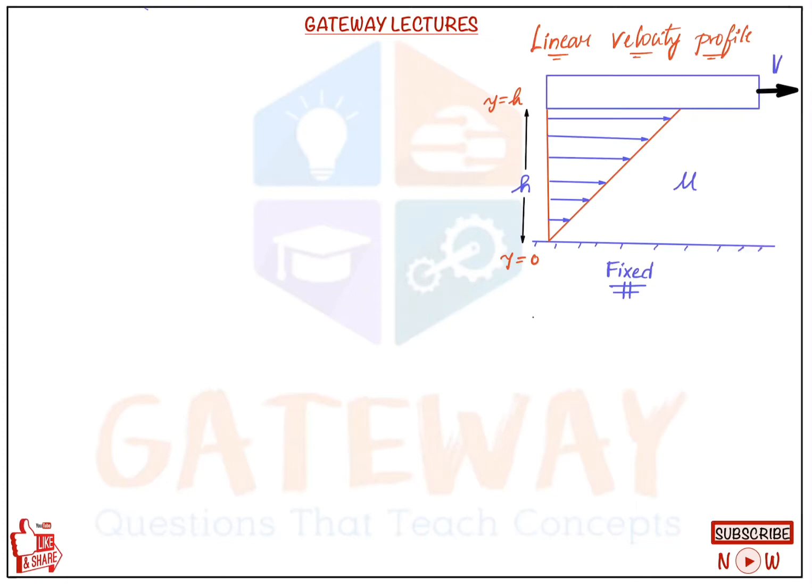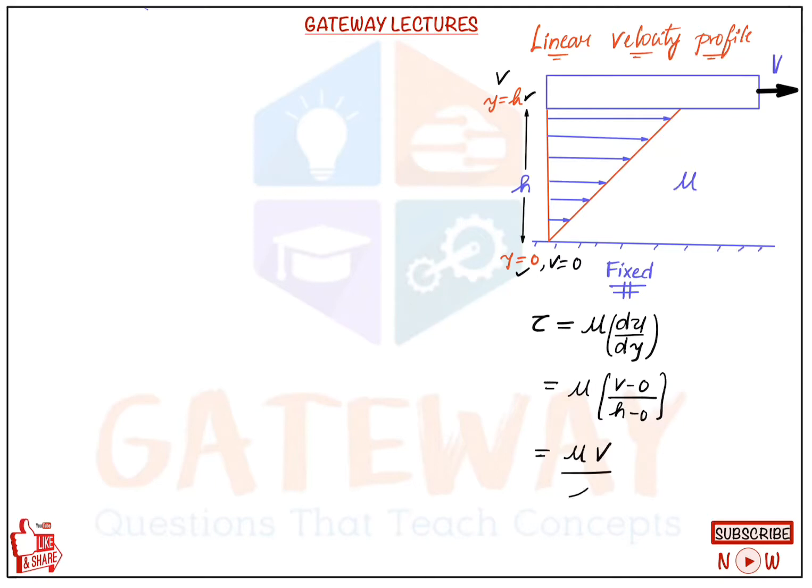As per Newton's law of viscosity, tau is equal to mu into du by dy. This velocity gradient is linear. For a linear velocity gradient, we know how to write the slope. Slope is nothing but du by dy. Here the velocity is 0 and here the velocity is equal to v. So du is the change in velocity, v minus 0, upon dy. Here the height is h and here the y value is 0, so h minus 0. So we get tau equal to mu into v upon h.